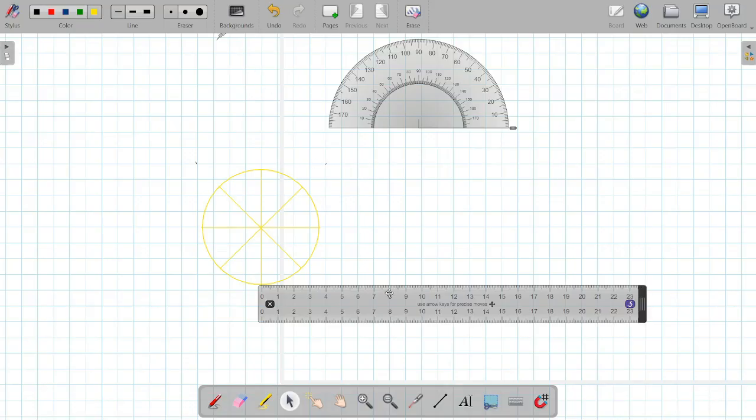Then after drawing the circle, we need to make a line, or let us say a horizontal floor, on which this circle will rotate. So as per the question given, it is rotating for one complete revolution. That means the circumference of the circle, the value of which can be calculated by the formula 2 pi r. So here r is 35. So 2 pi r comes out to be 219.8. So we will make a line of 219.8.